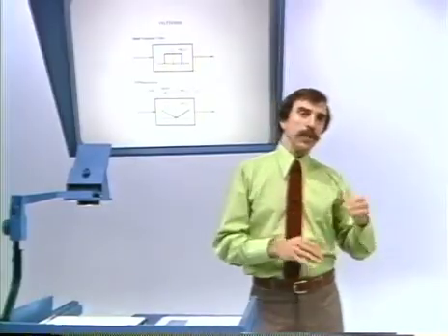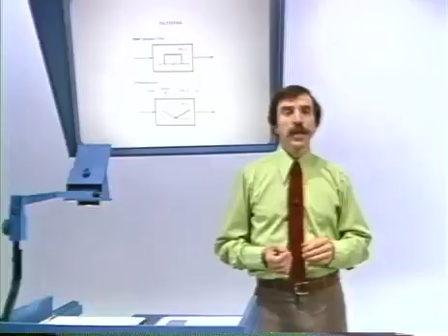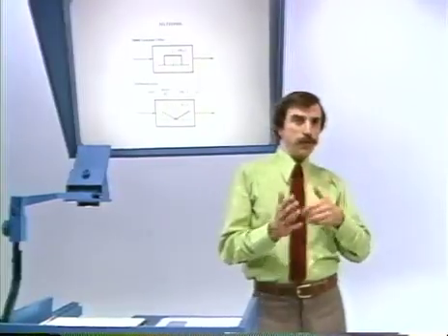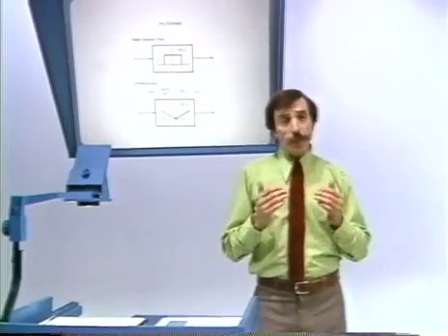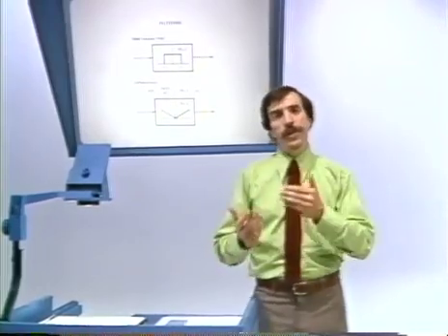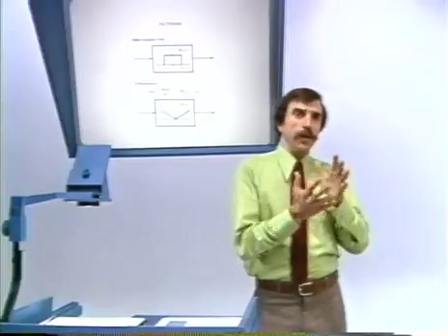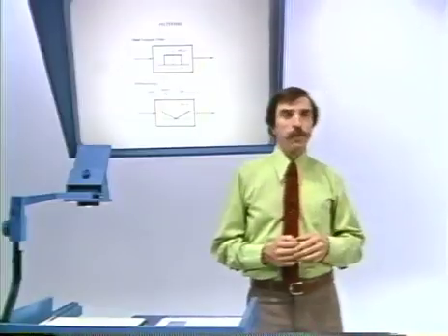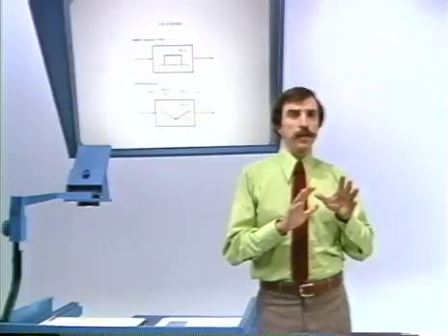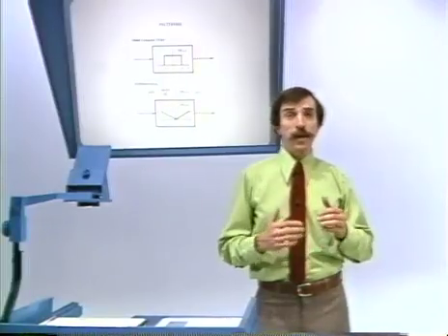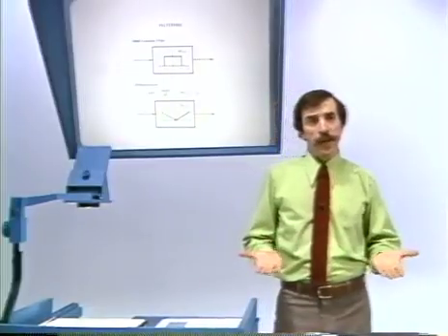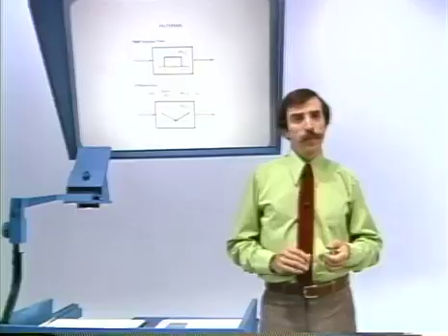Now, recall that this all kind of fits together as a nice package. We expect intuitively that differentiation will enhance edges. When we talked about square waves and we saw how the Fourier series built up a square wave, we saw that it was the high frequencies that were required in order to build up the sharp edges. And so either viewed as a filter or viewed intuitively, we would expect that the differentiated image would in fact attenuate the slowly varying background and amplify the rapidly varying edges.